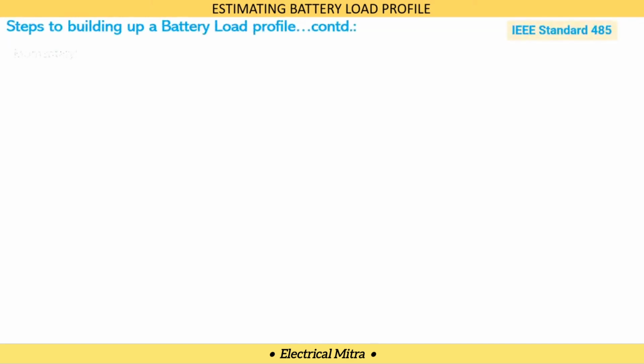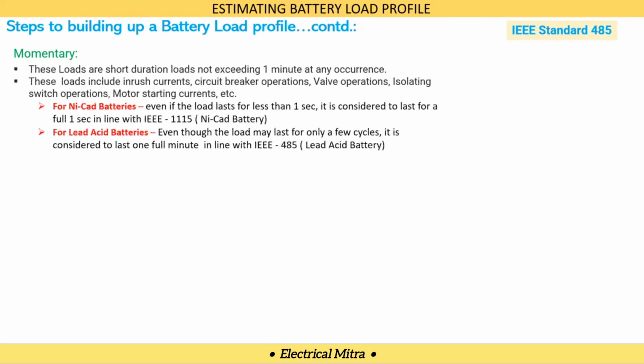Whereas momentary loads are short duration loads not exceeding 1 minute at any occurrence. These loads include inrush currents, circuit breaker operations, valve operations, isolating switch operations, motor starting inrush, etc.